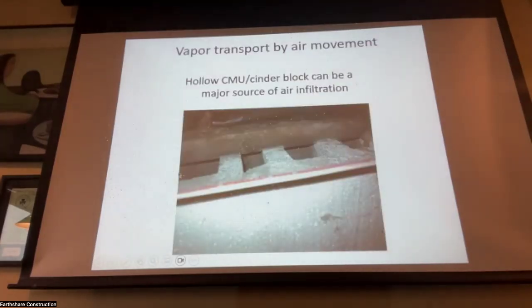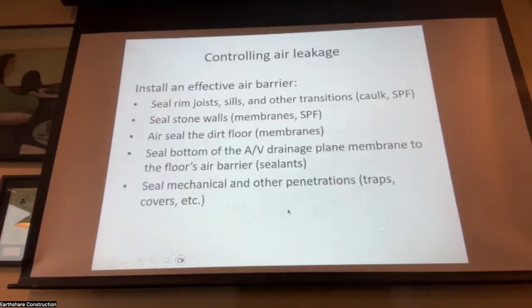So this is the big problem I see all the time: air coming in through concrete block walls. Because the sill is always 6 inches wide and the block is always 8, you always have this net opening. And depending on which side the mason was on, the joints are often not tight in these blocks on both sides.